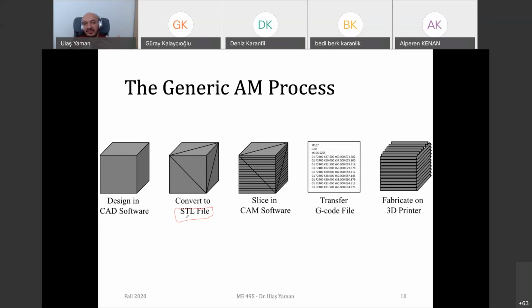The interior was nothing that important, since if you remember the main functions of additive manufacturing, we use it for form checking, fit checking, and function checking. So if these are the goals, then you don't need to focus on the interior of the parts.